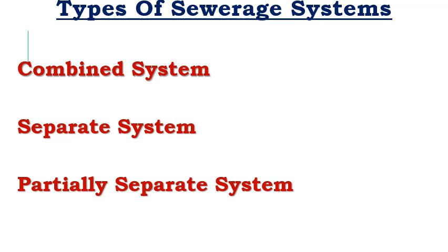This is called the combined sewerage system. Remember it. Combined means A plus B, the Q1 and Q2, the discharge, the available quantity of water. Coming from wastewater is one, sewage, and another is the storm water. That is the sewage and storm water. If you mix these 2 and allow them to pass through a single pipeline, this is called a combined sewerage system. Only one line we have to provide.